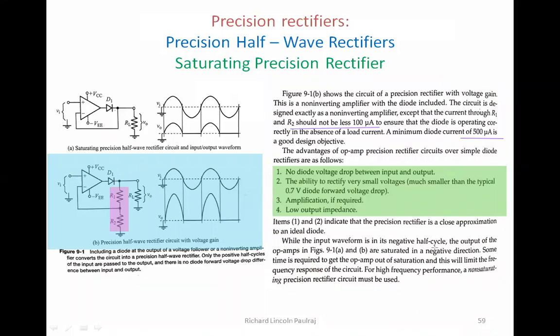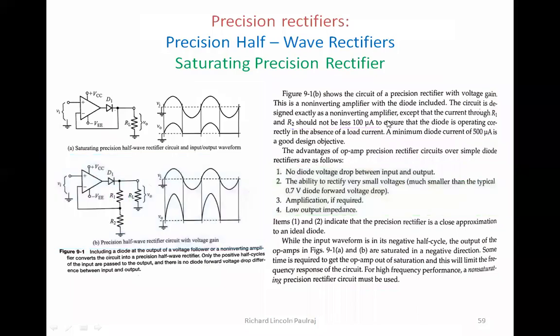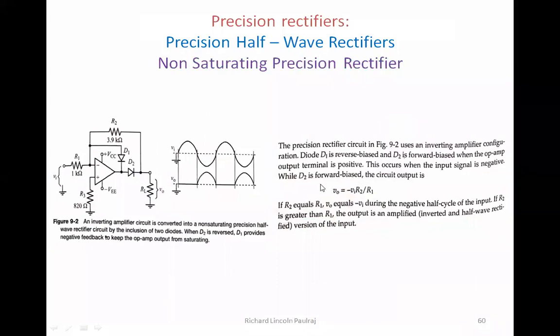Okay. Another important point is, there is some time which is needed to get the op-amp out of saturation, and this will limit the frequency response. So with this setup, the time taken for the op-amp to move from one mode to another, getting it out of saturation mode, is a little time consuming. So we will not be using this for higher frequencies, but instead we will use the other setup which I'm going to show now.